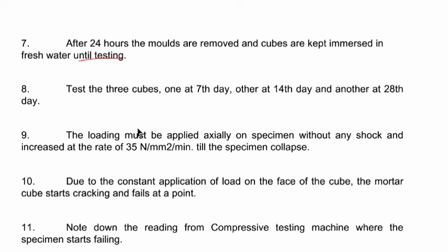The loading must be applied axially on specimen without any shock and increased at the rate of 35 Newton per mm square per minute till the specimen collapses. Due to the constant application of load on the face of the cube, the mortar cube starts cracking and fails at a point. Note down the reading from the compressive testing machine.